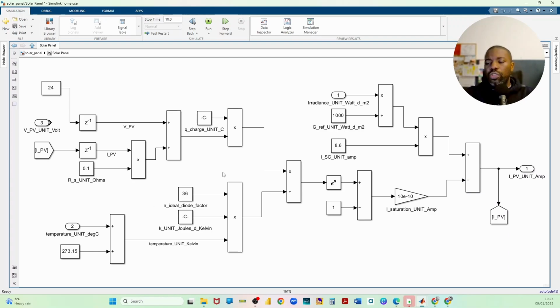Secondly, to be able to evaluate what this is trying to do, you can also model it not as an equation, but as lines and blocks connected to each other. The main reason you do that is because Simulink will allow you, when you simulate, to interrogate every single line that is connected while the data is being passed. This is critical for troubleshooting, unlike a MATLAB script, because it gives you complete control of every time step to directly identify where potential problems are. And we will go through that.